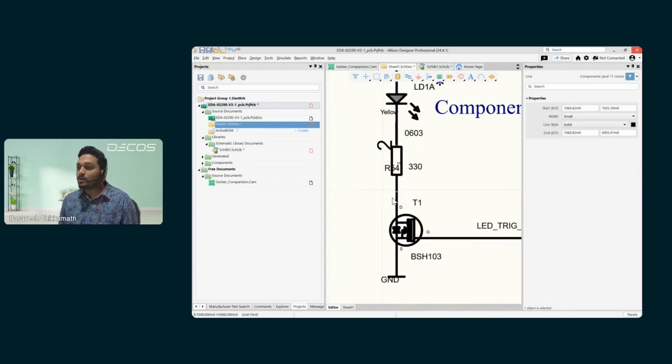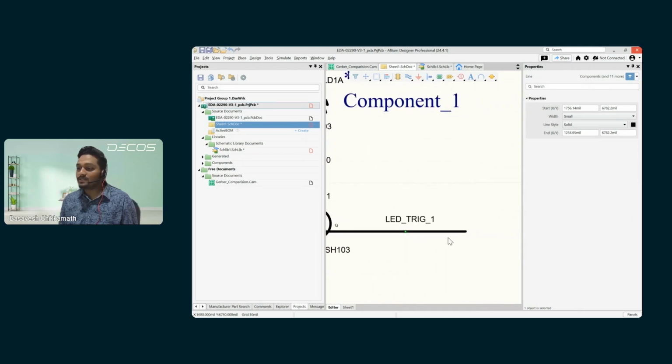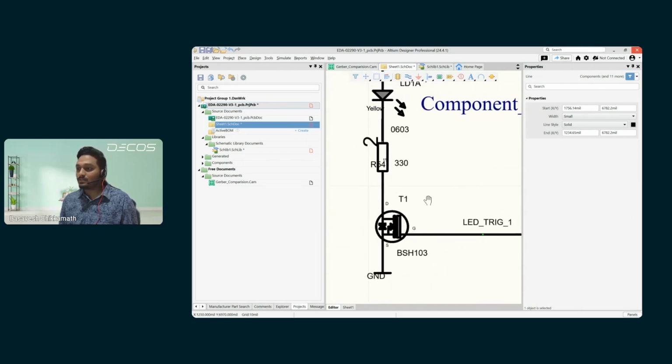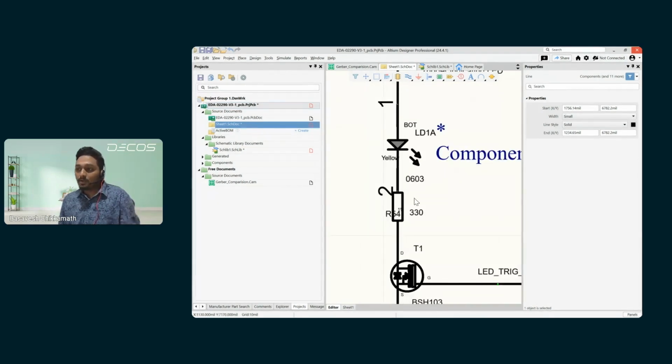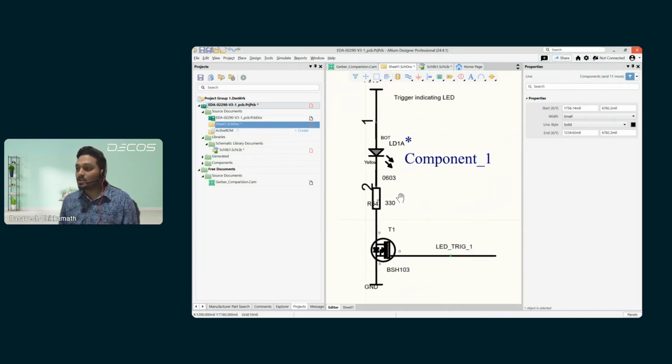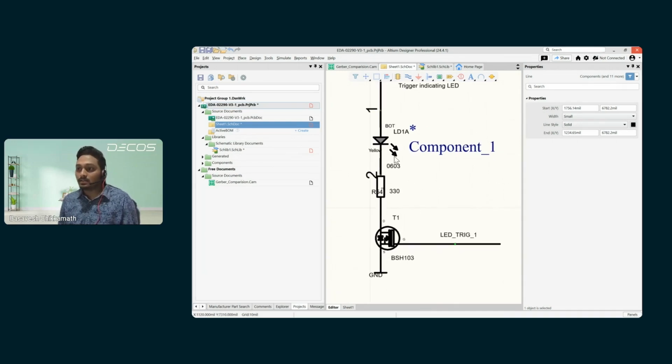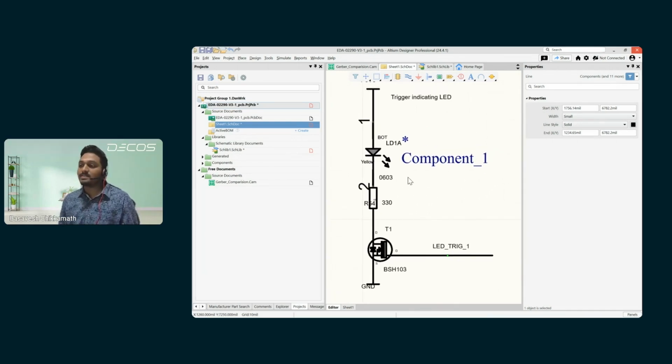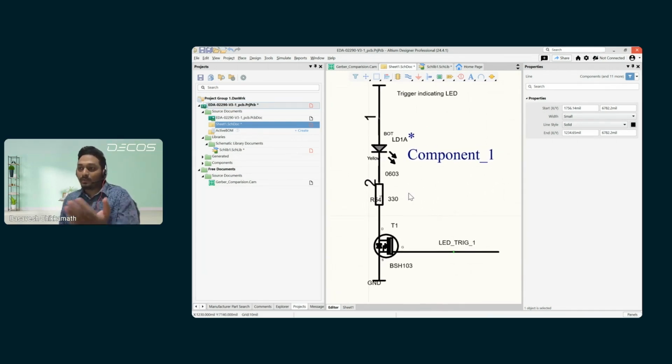Right now, since all those DXF lines are just C lines or free lines, you will not be able to wire or connect between the components. Only when you have newly created the components and you have placed them on top of the existing DXF component C lines will we be able to connect between the pins.